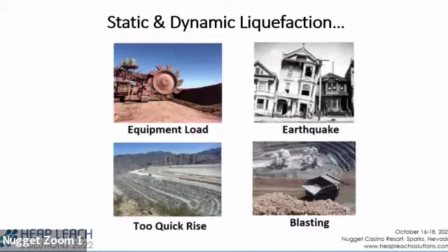That could be bearing capacity, but it could be static liquefaction or dynamic liquefaction caused by the vibration more than the weight of the bulldozer. Static liquefaction is a primary design constraint for upstream raised tailings dams. It will always be part of the operating criteria, and it will be expressed typically in meters per year. How fast can you raise your dam? How many meters per year can that crest go up?